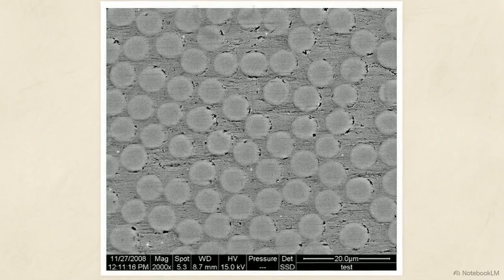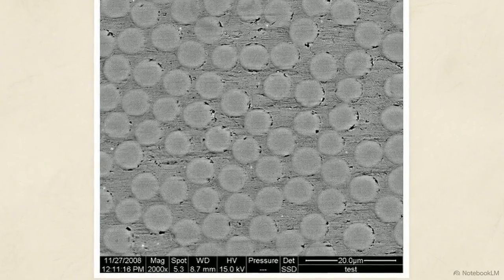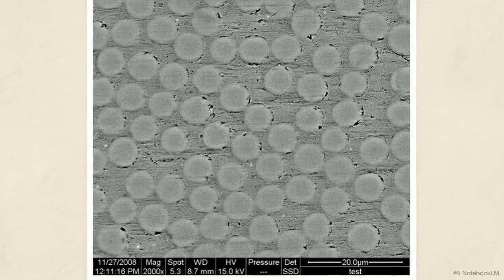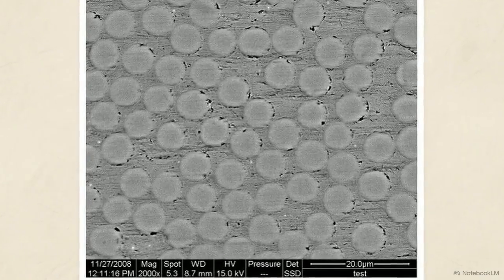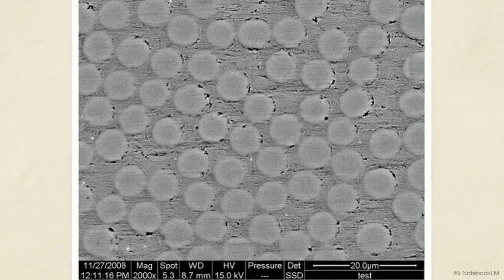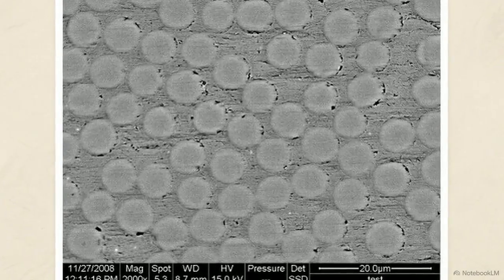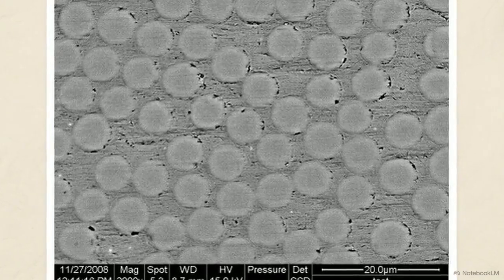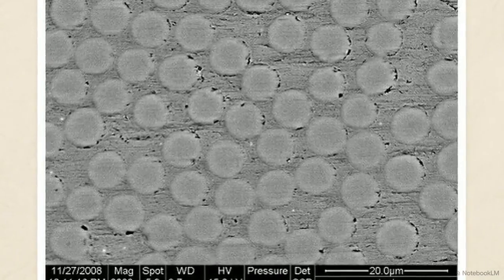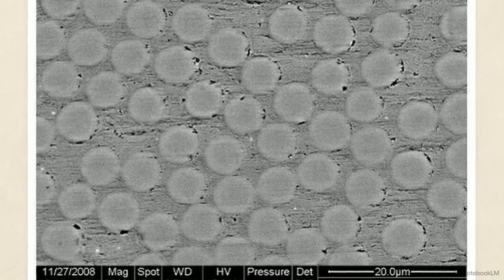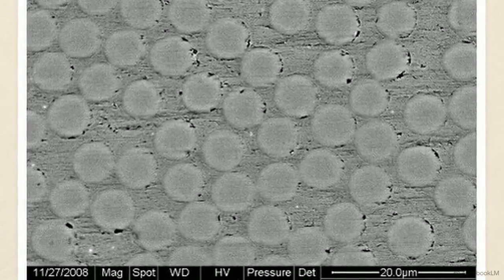But physical manufacturing introduces continuous spatial chaos. Real composites do not form perfect grids. This physical chaos produces critical structural defects. Within the cross-section, we find resin-starved regions where fibers clump tightly together, sitting immediately adjacent to resin-rich voids where fibers are entirely absent. In a theoretical, perfectly spaced grid, compressive stress distributes evenly across the entire structure.